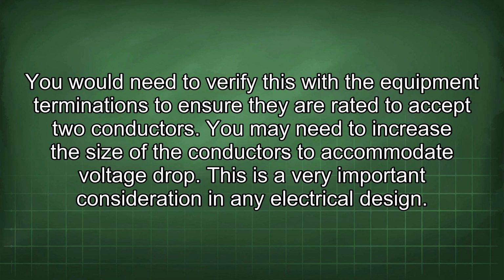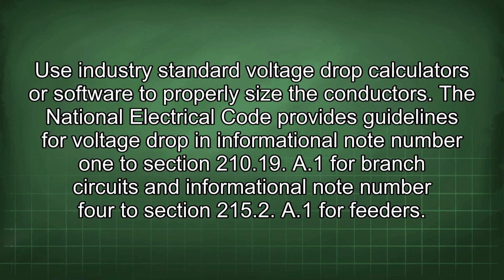You may need to increase the size of the conductors to accommodate voltage drop. This is a very important consideration in any electrical design. Use industry standard voltage drop calculators or software to properly size the conductors.